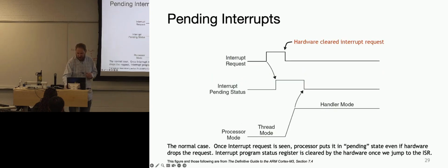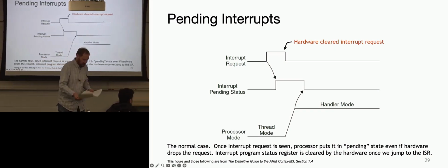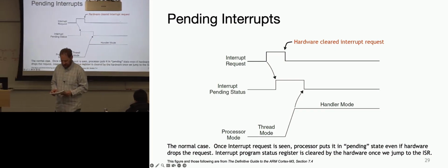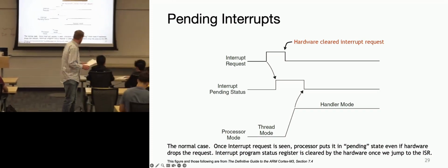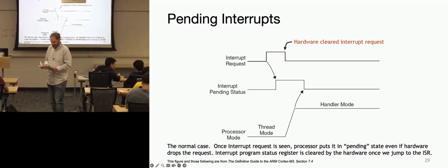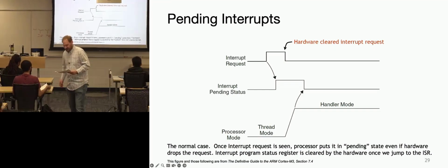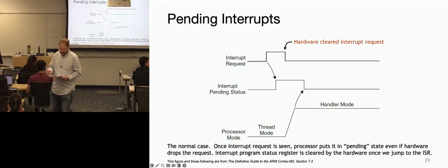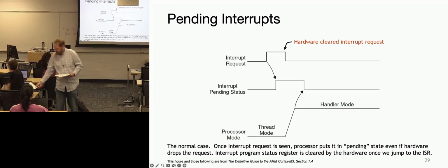We went through, I'll hand out these worksheets again just so you go through. We missed one of the interrupts, or one of the slides. Let's give you guys a chance to do it. So if we look on the slide, we see that the top is interrupt request. So that's the IRQ signal that comes from the peripherals. That's not a register state, that is just a signal, and there's going to be 96 of those. We're only showing one in these examples.